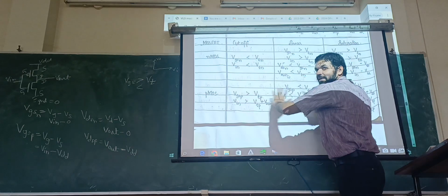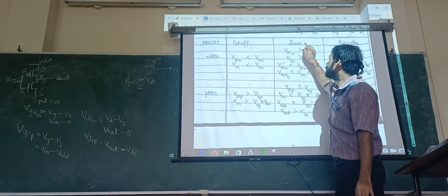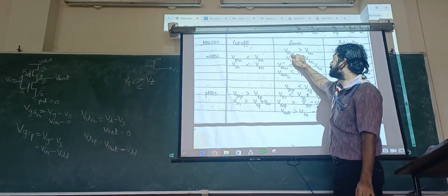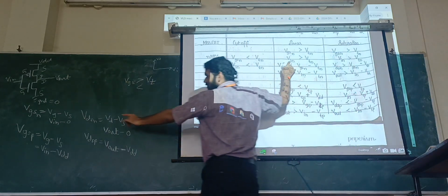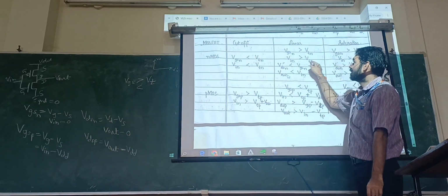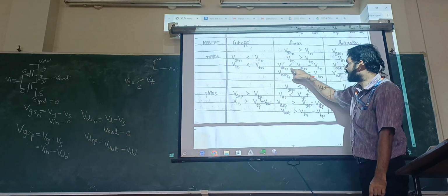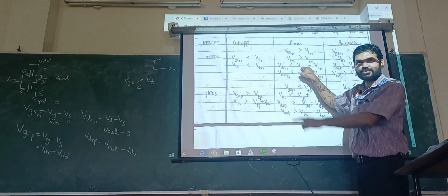Now here, VGS greater than VT. What is VGS? For N, again Vin greater than VTN. Okay. Fine. VDS less than VGS minus VT. These are simply just noted now.